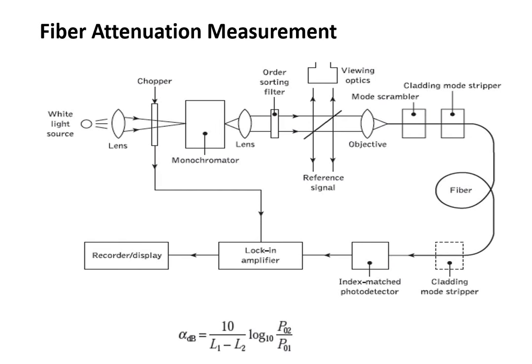The advantage of this method is that its output is very accurate and simple. Some of the drawbacks faced in this particular method: it cannot be utilized to find the fiber attenuation in a working fiber optical link. In that case, the optical time domain reflectometer, abbreviated as OTDR, is used. This cutback method is a destructive testing method.